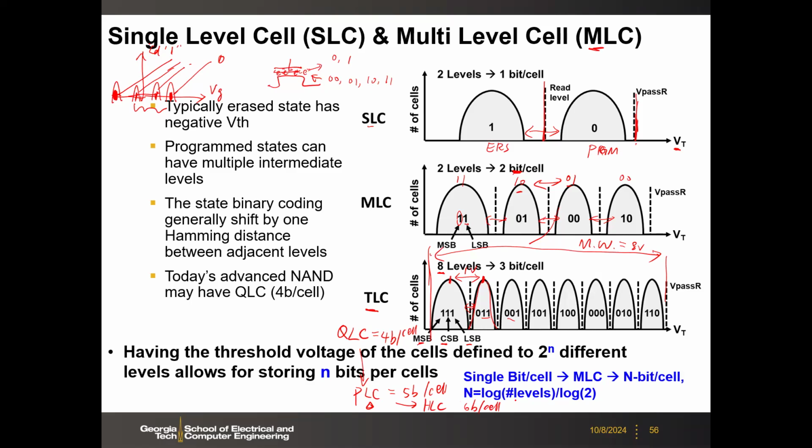For example, I remember there was a paper from Toshiba, or let's say Kioxia. They demonstrated this 6 bits per cell at a cryogenic temperature, like 77 Kelvin, because the noise and all those variations got suppressed. So they managed to get 6 bits per cell.